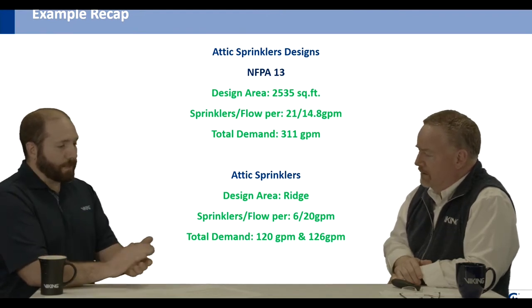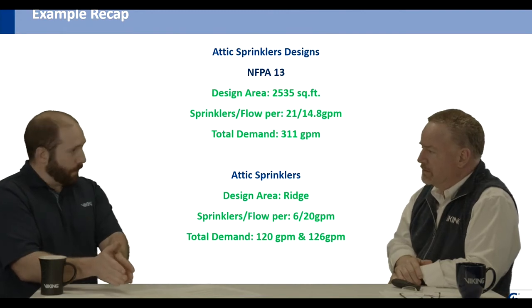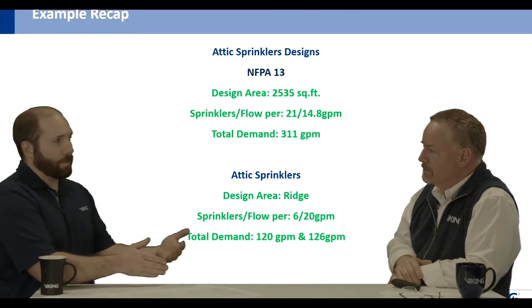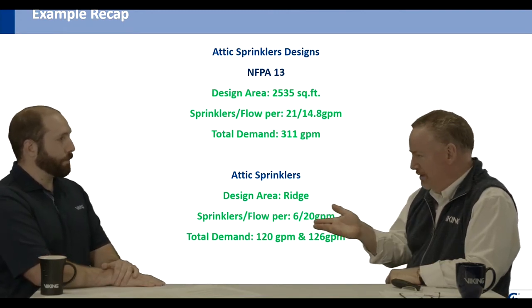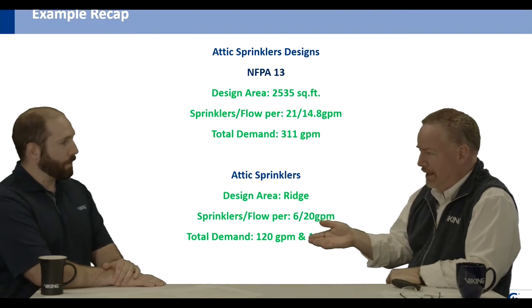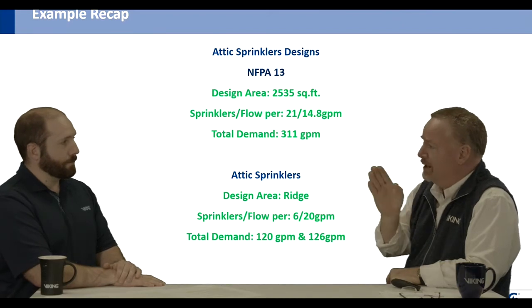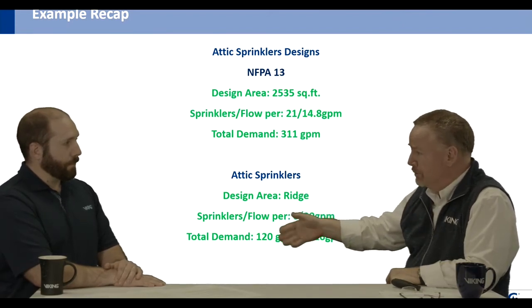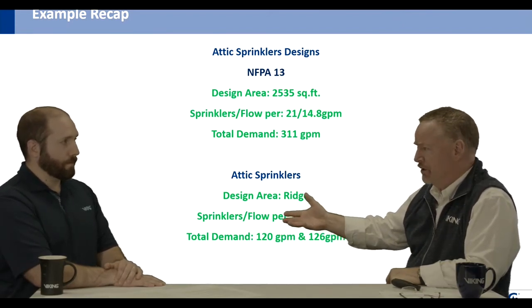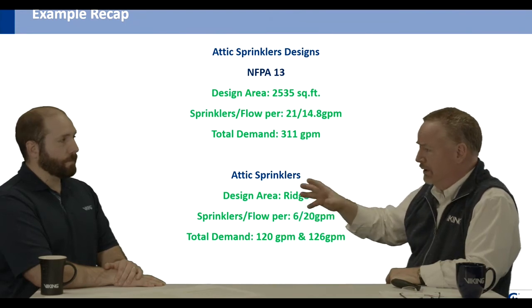And it's really designed, one, so we can get the low flow design, or two, for getting around obstructions. Right. I was just about to ask, you can use the attic sprinkler in combination, you said, with the back-to-backs or the single directionals, when you have obstructions out there greater than 6 inches, I think, in one dimension. Yeah.